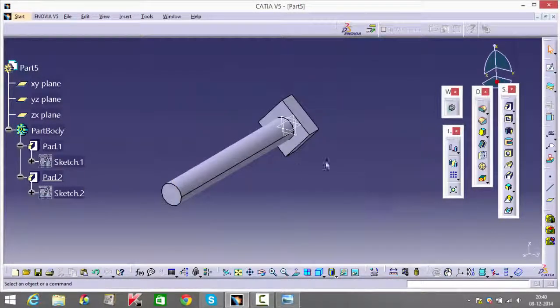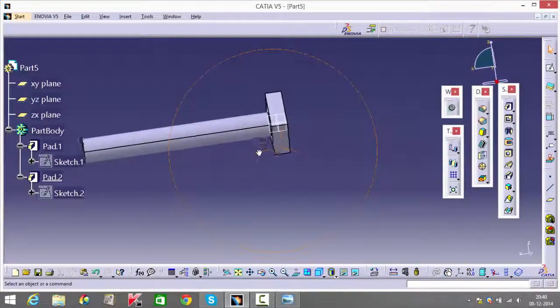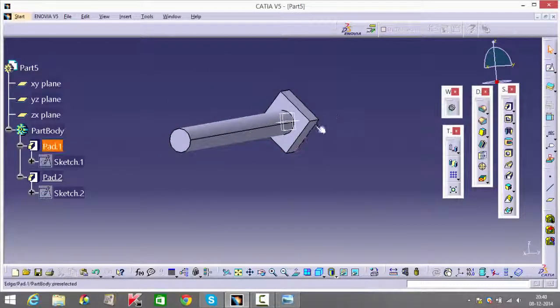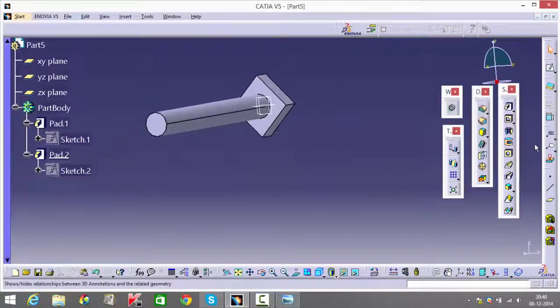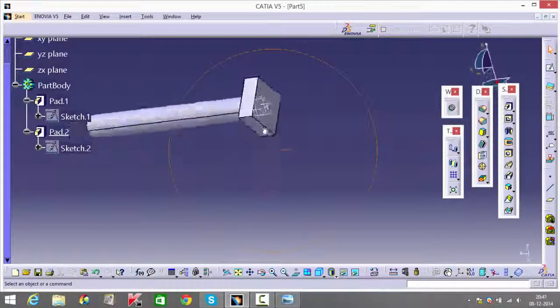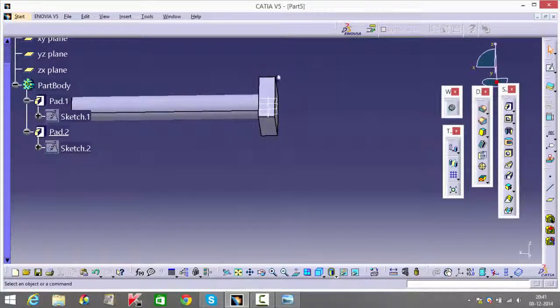Now the reason will slowly come up. Like I said before, I'm gonna use the groove option. For me to do that, I'm basically gonna draw a small triangle over here on one of these ends on the corner, and it's gonna groove that throughout.